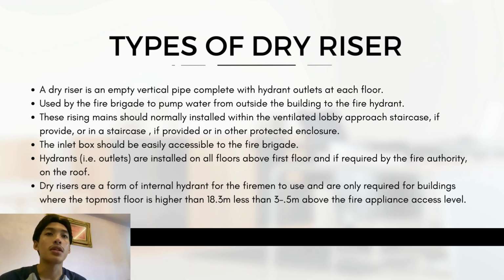Number 6. Dry risers are a form of internal hydrant for the firemen to use and are only required for buildings where the topmost floor is higher than 18.3 meters, less than 30.5 meters above the fire appliance access level.